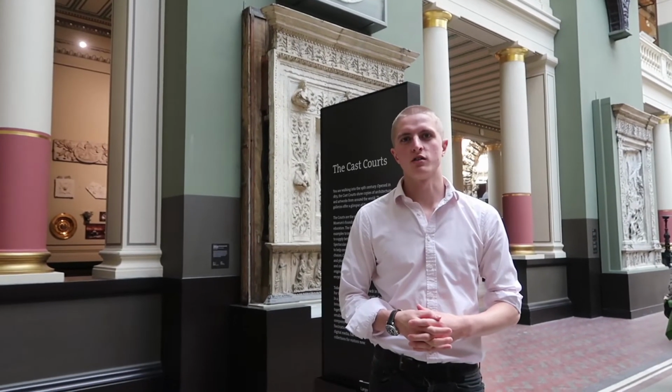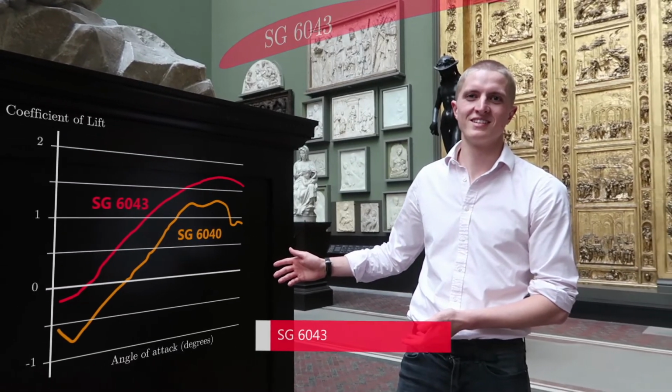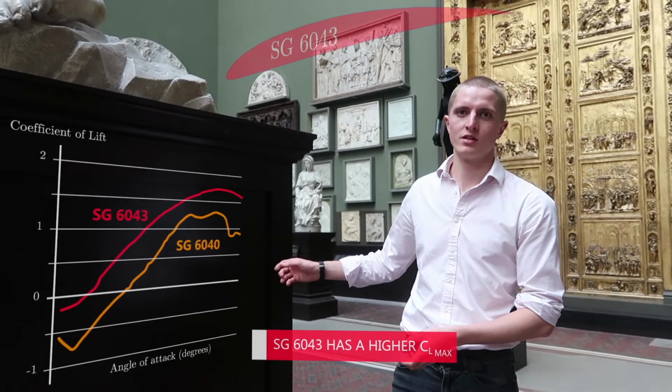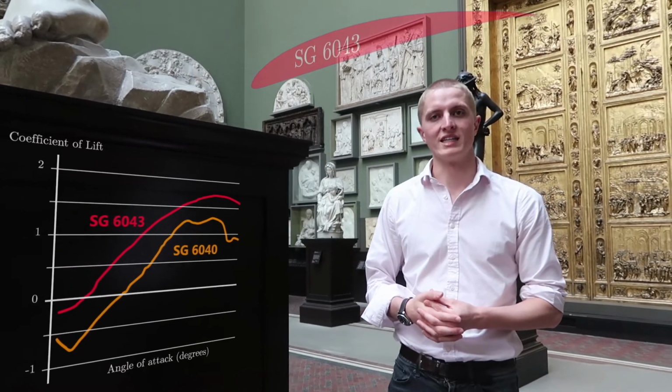So our first aerodynamic task was to choose which airfoil to use on our turbine. We first decided to use the SG6040 airfoil at the root because it had higher structural integrity, and we used SG6043 at the wingtip because it had a higher CL max and a better CL curve and aerodynamic lift. As we can see here, the 2 CL curves are of two different airfoils, and hence SG6043 was a better fit for the wingtip.